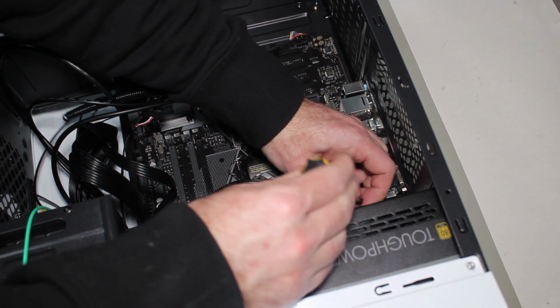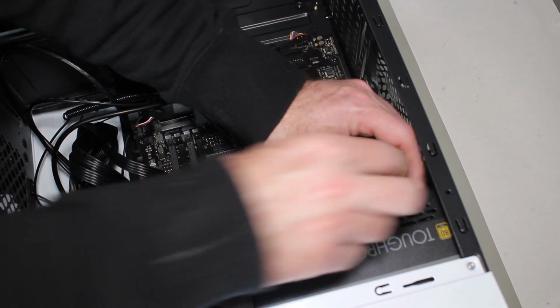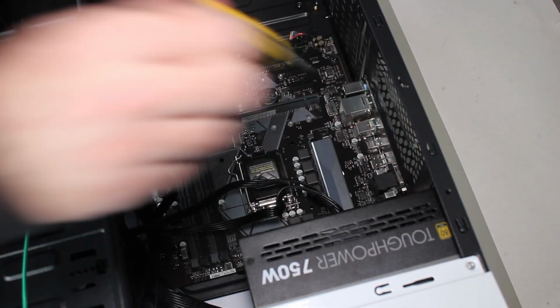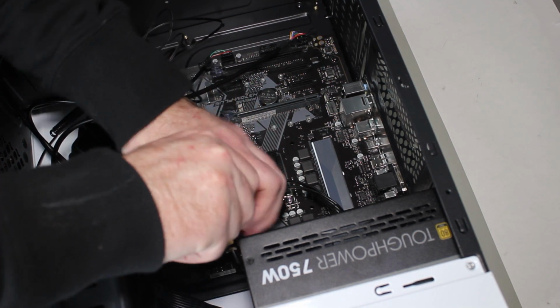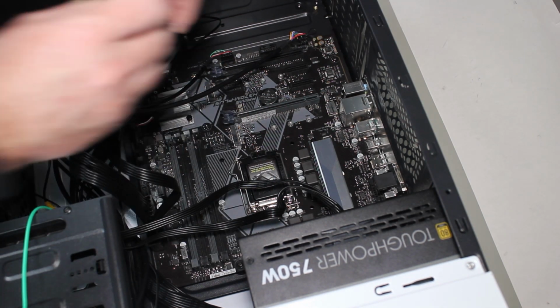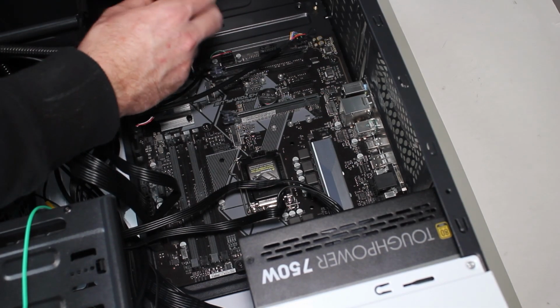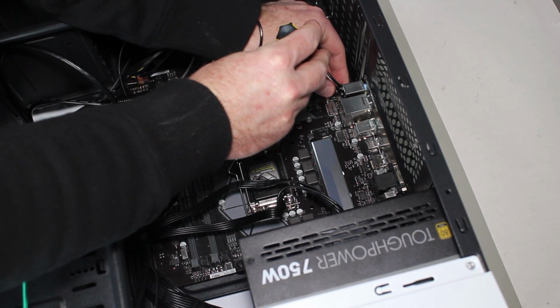Each screw only needs to be finger tight. Don't over-tighten them. This can cause damage, and if the thread is broken, will make it hard to remove the screw later on if required. I will put in all 8 screws, which I recommend that you do. If you don't have enough screws, at least put in the corner screws, which helps to keep the motherboard stable. Some screws are better than none, but you should put all the screws in whenever possible.